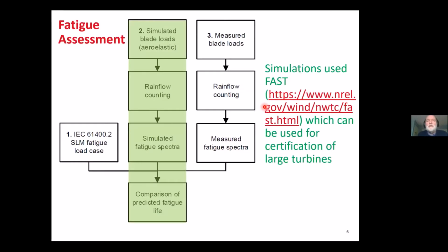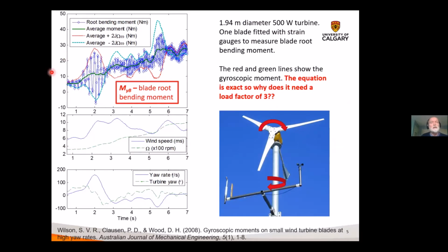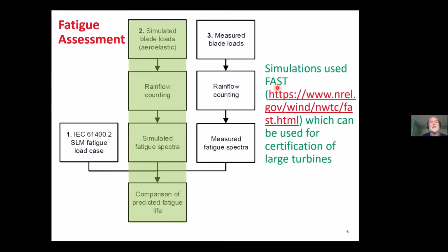Okay, so I'm going to move on to fatigue assessment because I should have pointed out the cyclic loads that are associated with the gyroscopic moments are also fatigue loads. And when we come to fatigue loads, we basically have three ways of doing a fatigue assessment in the IEC context. One is to use the equations in the simplified load model for fatigue.